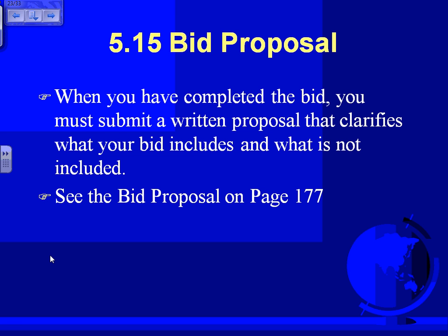Okay, so scope of work includes. What do you include in this one? A nice description of what you include. For example, the temporary electrical service pole, and all this description. Plans and specification. Proposal is based on the blueprint and the specification, if any. See how they save yourself. Now, I am basing this money on the blueprints E1 through E12 and the set of specifications. And issued, you see the issue date on it? Very important. So, you lock yourself in with the blueprint.